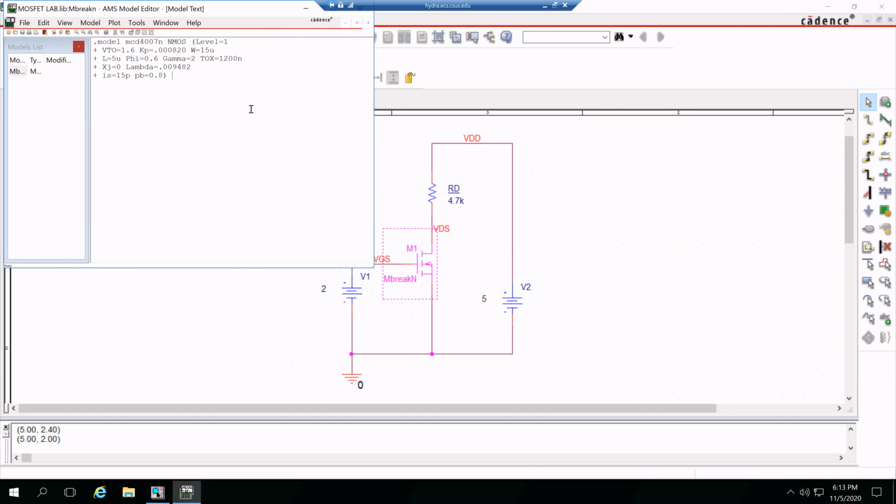So if it has a specific gate and drain voltage bias with respect to the source, this model would calculate what the current is going through the different nodes. If you have any background with curve fitting, it's based on a bunch of parameters. That's what all these parameters are in here for, for that model to make the curves match what is physically being produced at the manufacturing site.